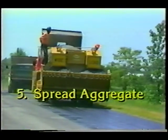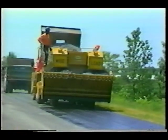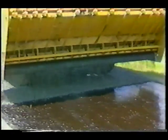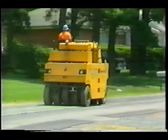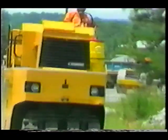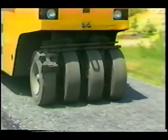Step 5, spread aggregate. Spread the aggregate immediately after the asphalt is sprayed. When using emulsified asphalt, spread the aggregate before the emulsion breaks. Aggregate must be clean so that a good bond can form between it and the asphalt. Step 6, roll the aggregate. Roll the aggregate immediately after the aggregate is spread. A pneumatic tired roller is recommended to roll the aggregate. A steel wheel roller may crush aggregate or bridge over low areas.